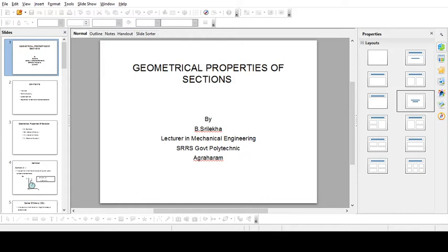So 3r by 8 is the value of the centroid for this. Okay, this is how we calculate the centroid. So x term is r and y term is 3r by 8.